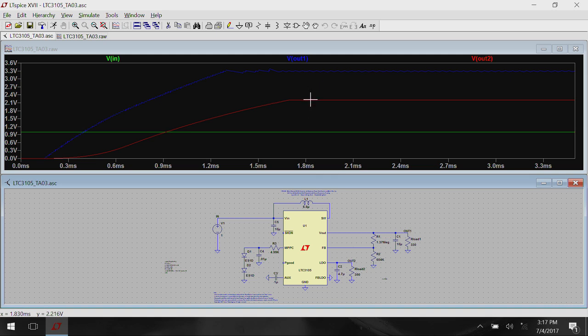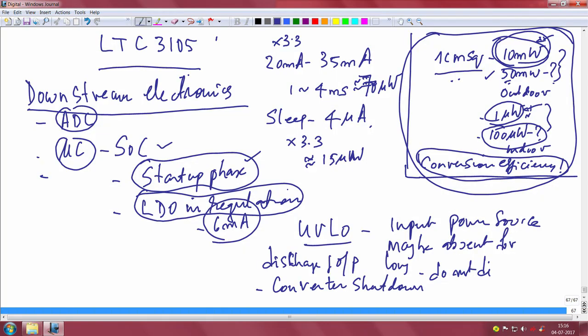From the chip specification, you cannot draw too much power from this. What you can draw is only a current of about 6 milliamperes. Again, this is what the data sheet says. So, you can at best switch on the microcontroller and perhaps do some basic sensing, that is all you can do with the LDO output.